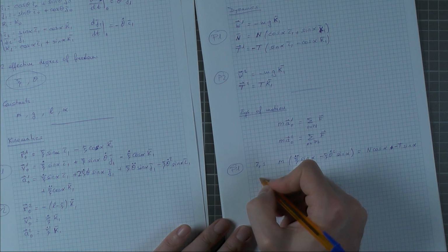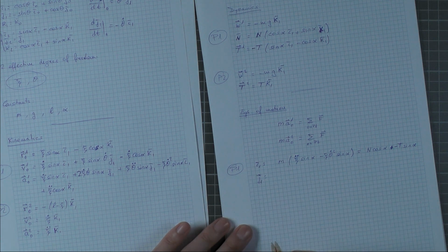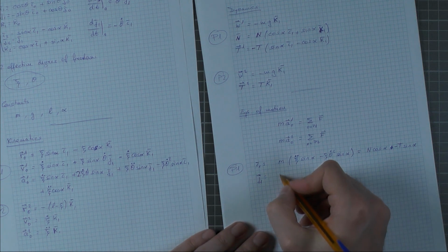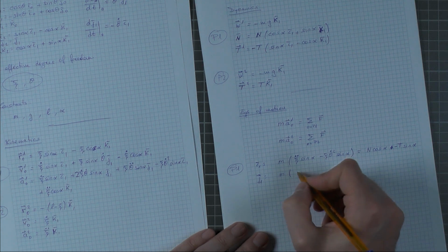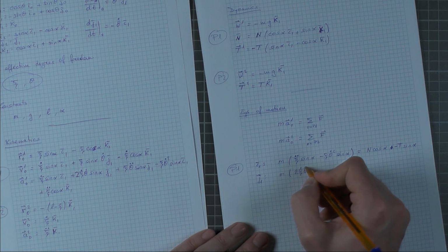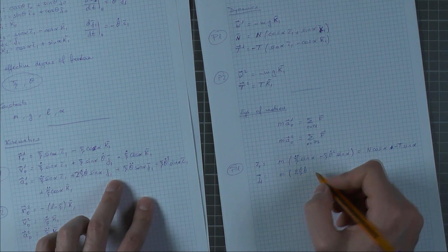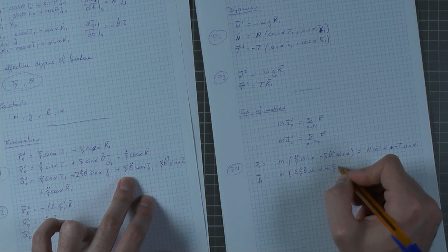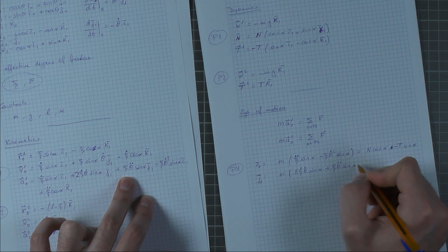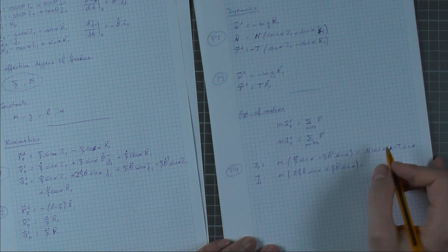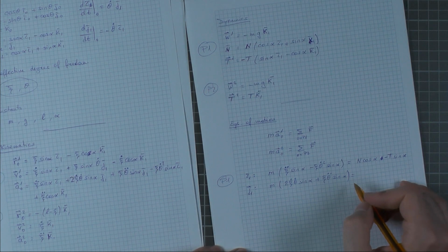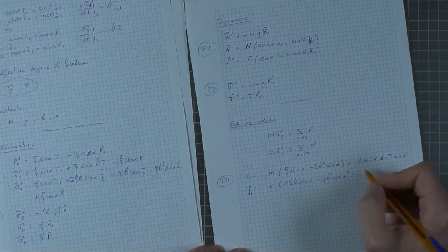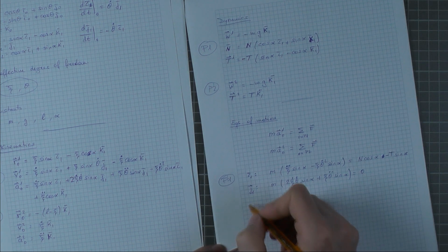Let's move on to the projection along J1. Here we have these two terms of the acceleration of P1 that we must consider. So there is this one times the sine of alpha plus this one sine alpha, and then all the terms that go in the direction of J1 in the forces. As you can see, there is none. That's an interesting result. We just have to write a 0 over here.